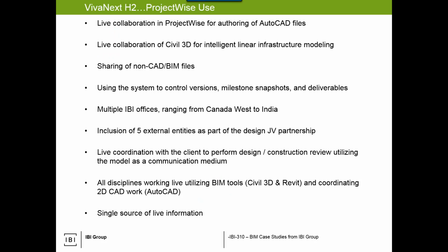It also used ProjectWise for live collaboration, with AutoCAD and Civil 3D files. It had a complex Civil 3D data shortcut. If you're familiar with Civil 3D, a data shortcut allows you to share. I define an alignment or a pipe network once, and that definition can be used on every single project, or every single file within the project.